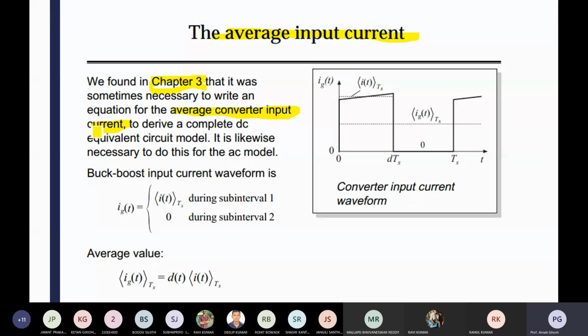Definitely there are some specifications: it should be a converter below 100 watt, maybe 50 watt, so you can design that way, with the inductor in the microhenry range. But if you go for a larger inductor value, the specification will be different and the converter rating will be high. A high rating may be responsible for additional energy loss.